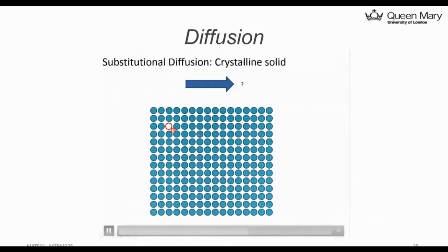You will see soon, it is called substitutional diffusion, or we can also call it vacancy diffusion, because if you have a vacancy here without an atom, that's a free space for the atom to move. Here you see that the vacancy is available for all directions.